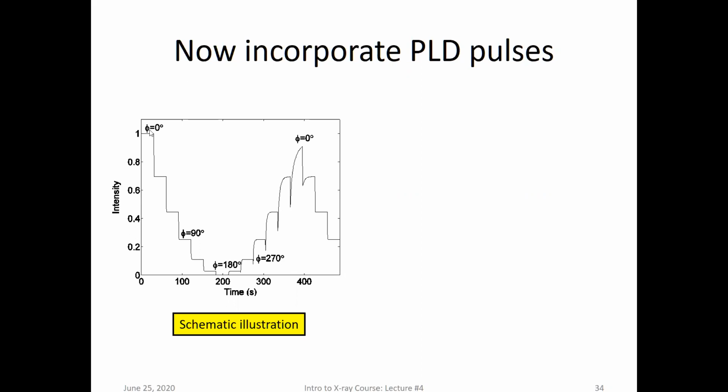And so we expect to see something like this, where we start with high intensity and the first pulse makes the surface rougher and rougher, until about half coverage, when it starts to fill in and come up. But if I wait between pulses, then it can anneal. The stuff diffuses around on the surface. So as I drop down, I don't see any recovery, but coming up, I expect to see some kind of rounding.